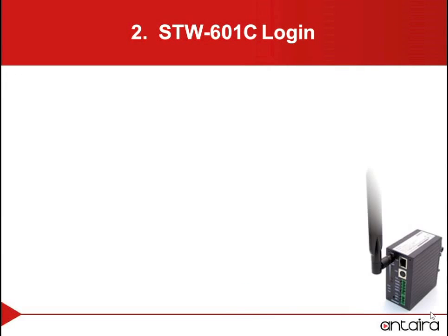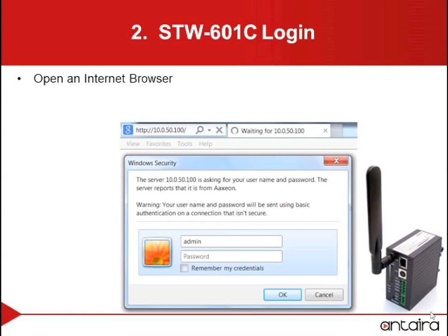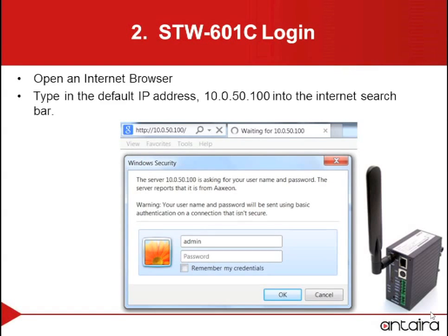To log into the STW-601C, we will open up an internet browser. We will then type in the default IP address of the device. The login information for the device will be defaulted as admin for the username, and the password will be left blank.